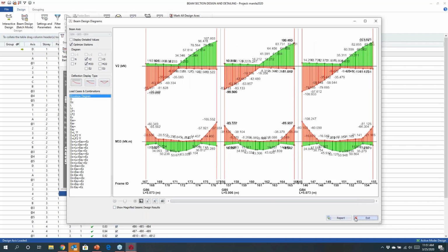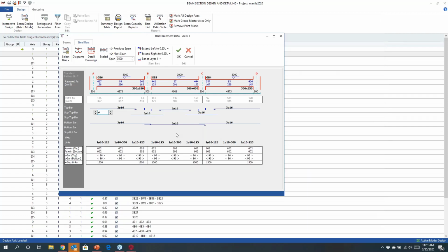Now, what we do for the design is that we will firstly apply the longitudinal bars. We will work out, based on what's actually provided, the moment capacities at each end of the beam, and then we will work out the shear design based on critical shear. So we will take the moment capacities divided by the length, and we will obtain the critical shear, and we will design our link arrangements here based on critical shear.